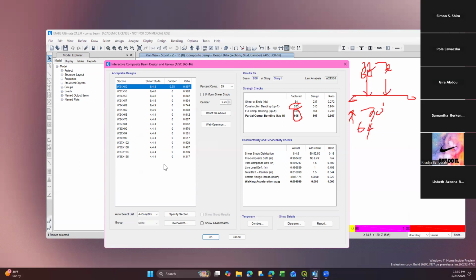If this is the case, it's 10 feet, 10 feet, 10 feet. Oh, this is bending. Yeah, 32. Okay, this is shear. Wait a minute, this is the shear at the end, so this must be 64.